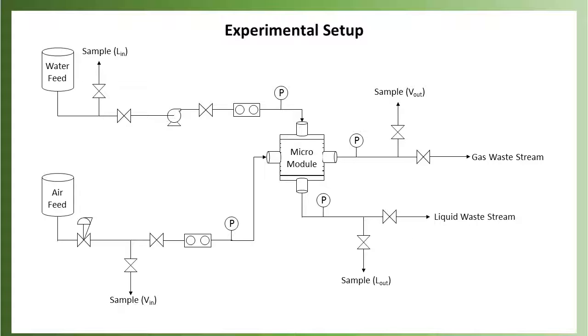On the tube side, so the water's going through the shell side, on the tube side, I've got zero-grade air coming through, and I'm controlling that with, at the beginning and end of the experiments, I'm using a bubble calibrator to make sure that my flow rates are similar throughout the experiment, and that is being pumped through the micro module, which I have a sampling port on the outside to complete the mass balance with the air and make sure that there's no losses in the system.